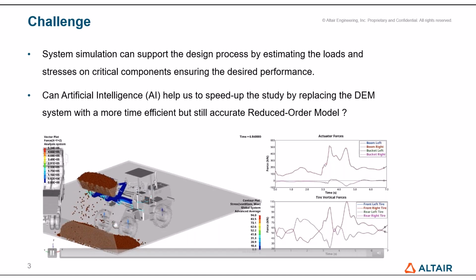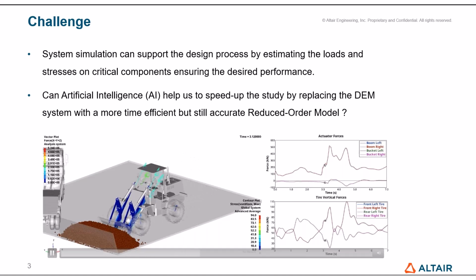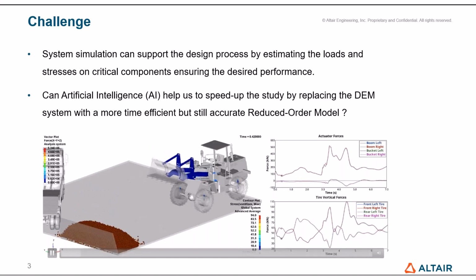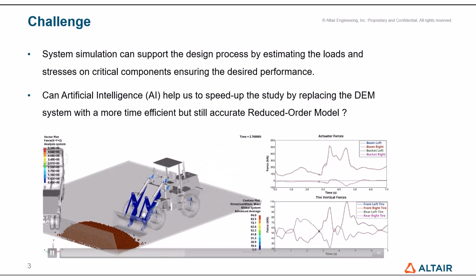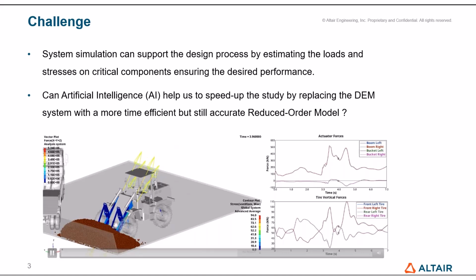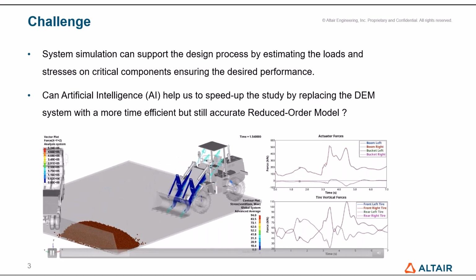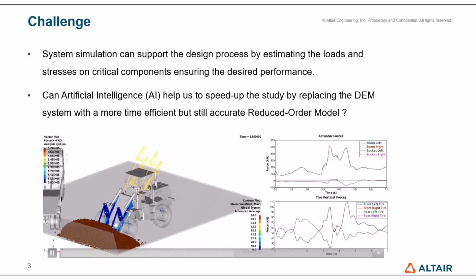So in that context, you would need something for simulating particle interactions with the bucket and also the particle interactions with each other. In that respect, DEM or discrete element simulations come very handy, and there is a tool which can do DEM simulations. But for now, the main point is that DEM is necessary to do particle and particle-equipment interactions, and DEM is inherently a very computationally expensive solver. So it will take a very long time to do this.